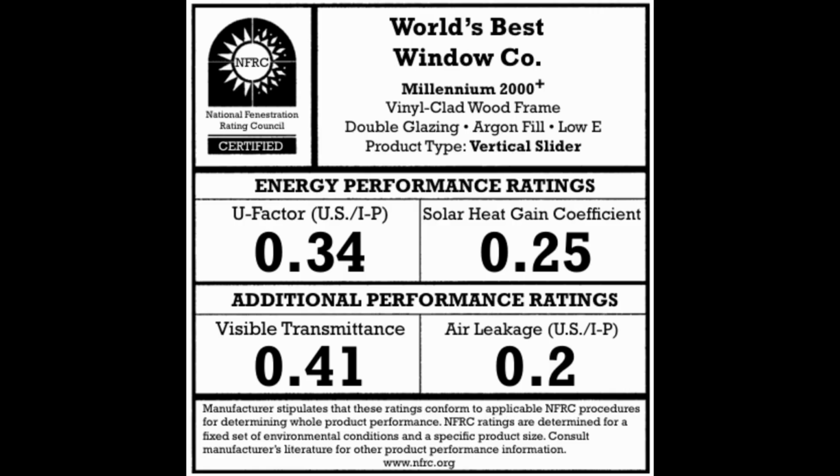Thermal performance. The National Fenestration Rating Council, or the NFRC, defines a program of energy efficiency testing and labeling based on 2 standards, the NFRC 100 and the NFRC 200. The most important properties included in these standards are thermal transmittance, U factors, and solar heat gain coefficients. U factors represent the overall thermal transmittance, or whole product heat loss, of complete window, door, and skylight products.